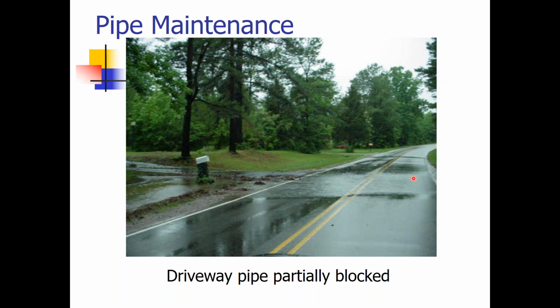But again, and this goes back to what we talked about on Tuesday and have covered today, water in the roadway over time is going to cause that roadway to erode. You can already see erosion taking place, not just from the soil. It's going to cause cracks to begin to develop. The water eventually will work its way down into the subbase, into the subgrade. We already saw that if we don't get good compaction, we're not going to have a good road. So if you start inserting water underneath that good compaction, that water is going to start turning it muddy and wearing that area away. Eventually you're going to have a depression over the roadway in addition to the cracks and the other issues that are taking place, and not only for the roadway, but on the sides as well.